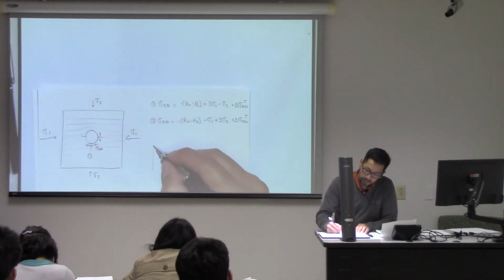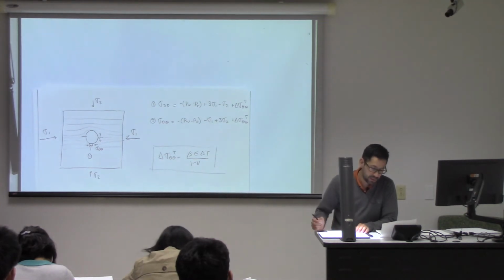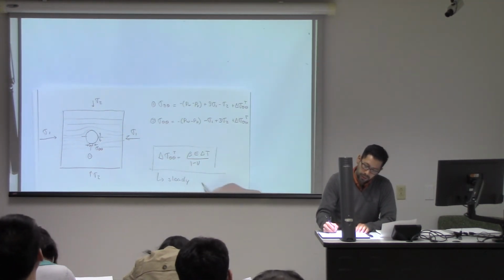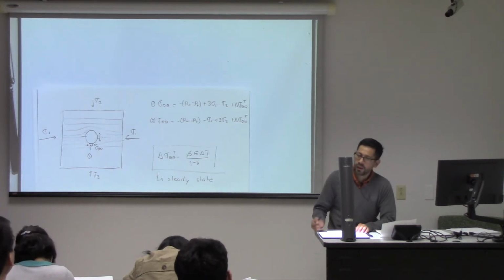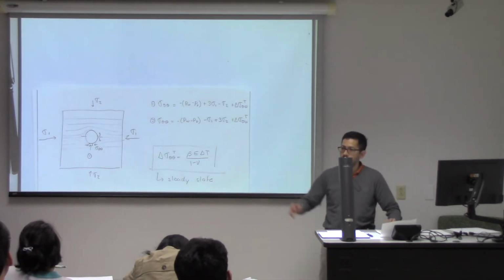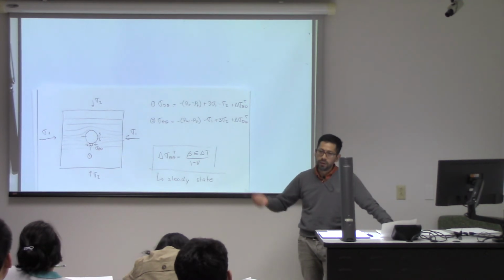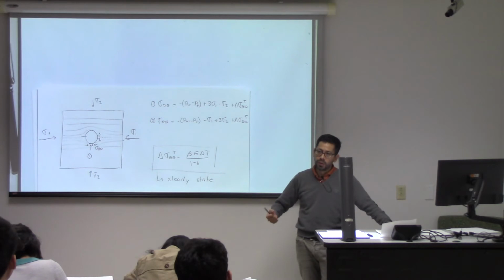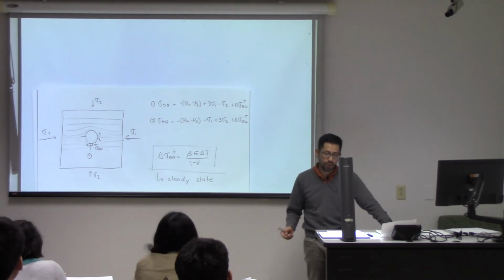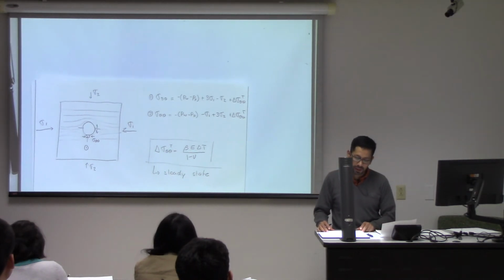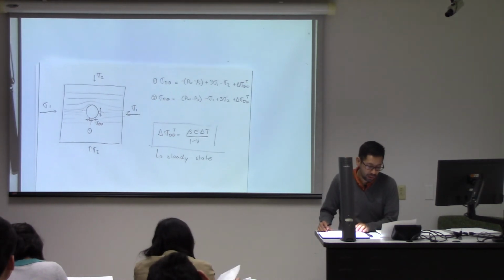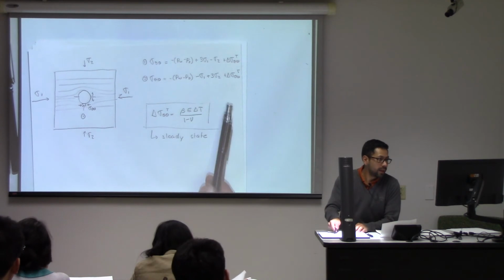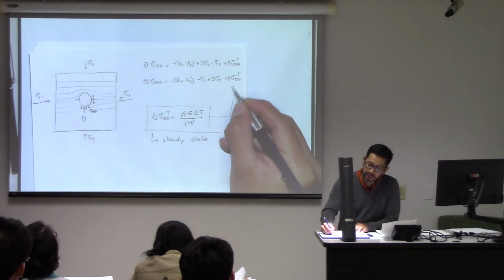And it happens that sometimes you can be drilling a wellbore and everything is fine, but once the rock starts to cool down, even maintaining the same mud pressure, the wellbore may fail because you're favoring the initiation and the propagation of some of these tensile fractures. So this solution is the steady state solution.